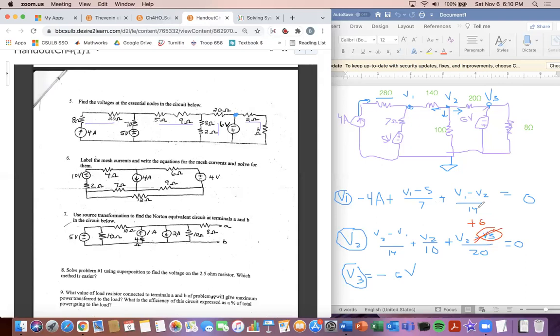My bad, Brian. Before you continue, let's say there was a resistance right above the -6 volts. Then we'd have to write a whole equation, right? Yes, for this V3 you would have to write a whole equation like we had for V1, because you see how we have a resistor here. Yeah, so what about the 8 ohms to the right? Do we just completely ignore that too, because we know the voltage is -6?